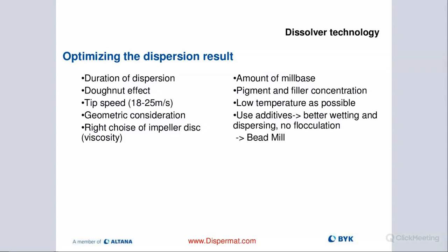So therefore, it's important that you have the right type vessels. And if you are pre-dispersing material that is very viscous, I highly recommend that you also use some sort of cooling, because you're going to put in a lot of energy. And again, when you're milling, you're going to need it anyways. So you may as well just get it up front. These are jacketed vessels that allow you to hook up a chiller or tap water, and that will circulate through the vessel and then keep the temperature as low as possible.